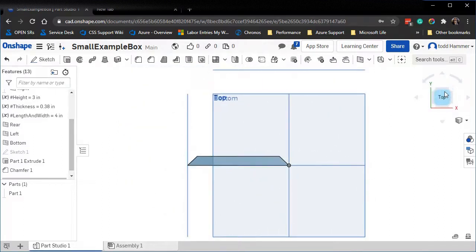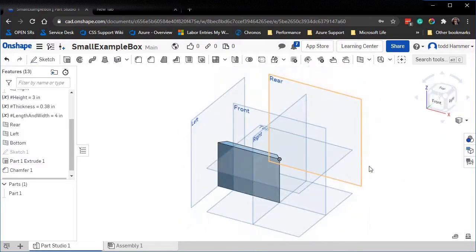So we can say, look at the top. I see, okay, I got my 45s, I got my parts all constrained. Let's go trimetric. And notice this down here, see this little tape measure? Let's select that, and now I can start measuring stuff. If I want to double check my work, okay, the length is 4 inches, nice. I'm going to click out here, click that vertical, 3 inches, nice. I could even go point to point, and it'll tell me, okay, that's actually 5 inches across, but by the way, in the x-axis it's 4, in the z-axis it's 3. So very handy little measuring tool.